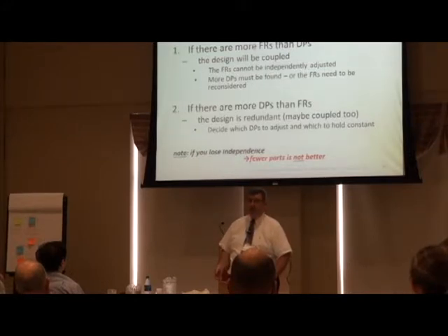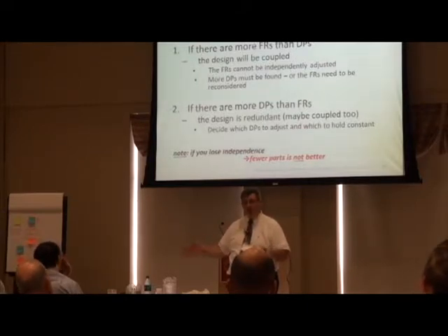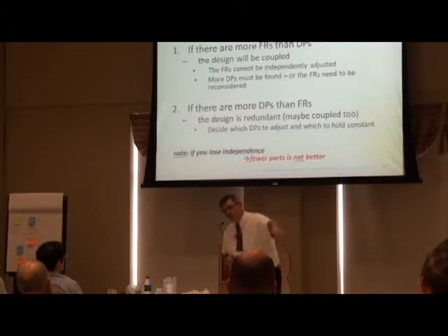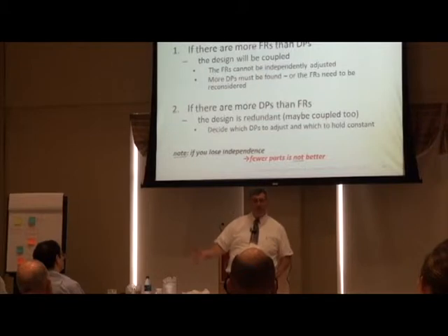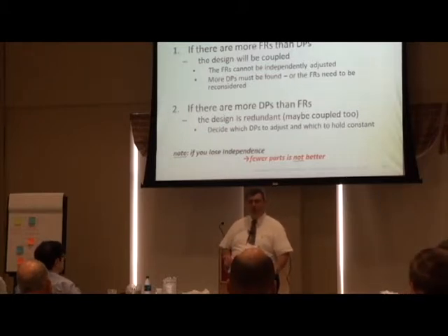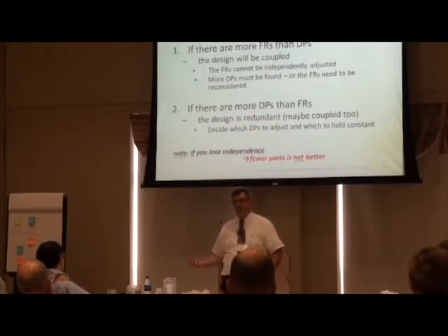And so they tried that for a while, and when it went out in the field, they found that when either one of the other pumps failed in the original system, you were still able to either move coolant through or cool the reservoir. But when you put the cooling fan on one end of the motor and the pump on the other end, when the motor failed, you lost both the ability to move coolant and cool the coolant, which caused things to melt inside the machine. The customers were very unhappy about that.